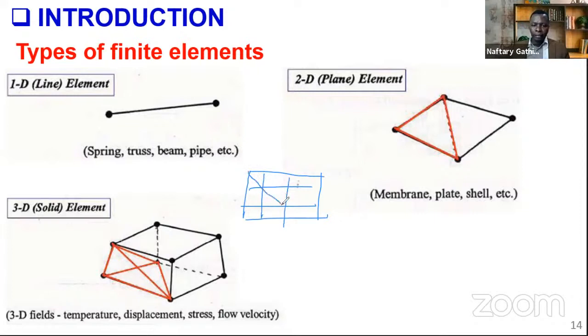And now we are employing the 3-node plane element, the constant strain triangle. I'm assuming this head is fixed, and then I apply a load on the other head, maybe a displacement, I pull. So you may want to get, at any point at distance X from the fixed head, where the total length is L,